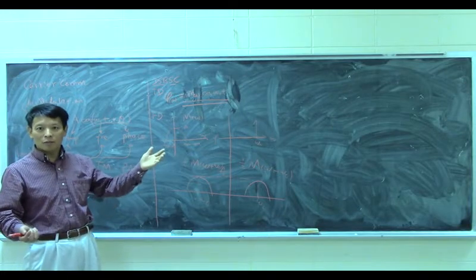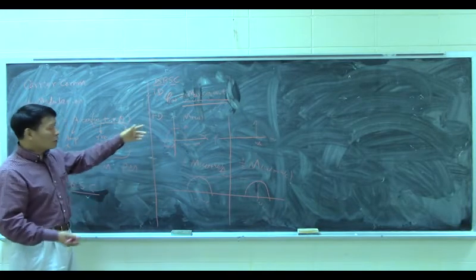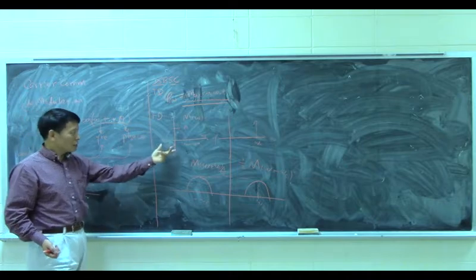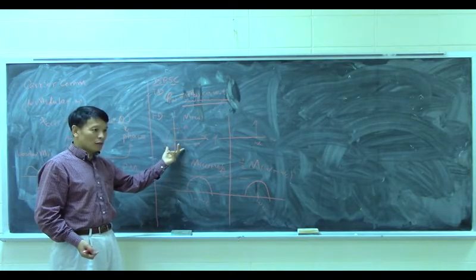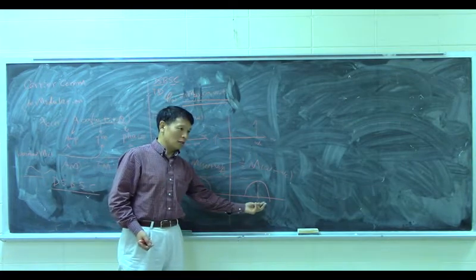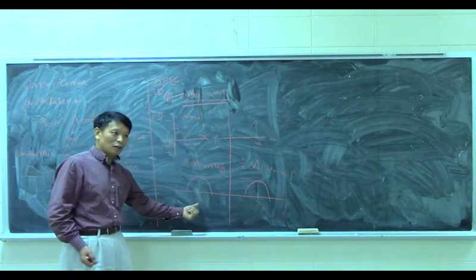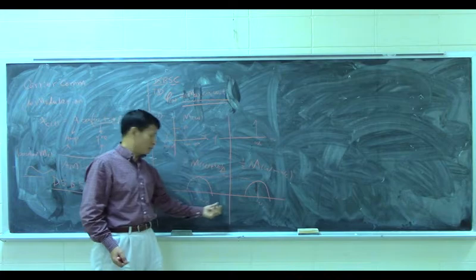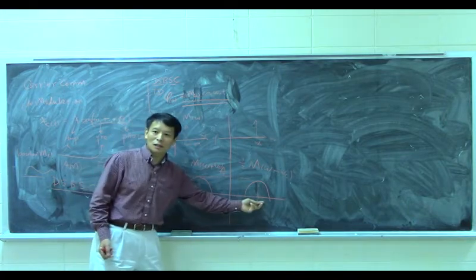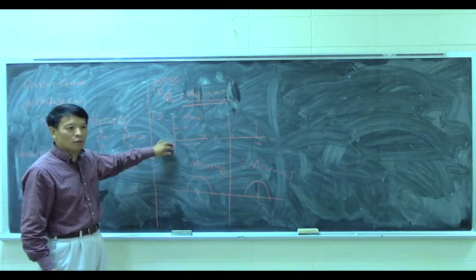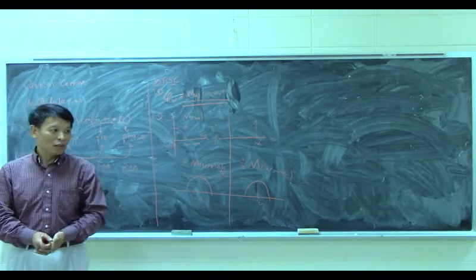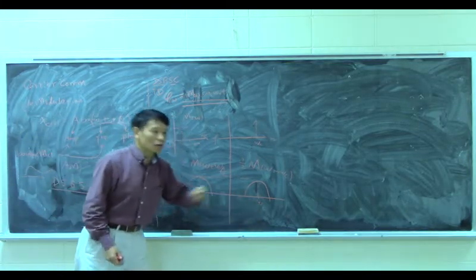That is in time. In frequency, this is the information you want to transmit. You just shift this frequency to a higher frequency. This one is still higher, right? This negative omega_c is still very high because this one is exactly the same as this one. So you just shift your baseband information frequency to a higher frequency, centered at the carrier signal.